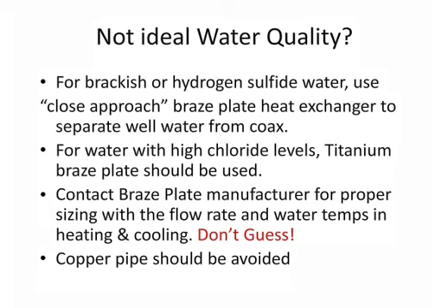Water with high chloride levels, again, you want to make sure that that close approach braze plate, I suggest, is a titanium. Always contact the manufacturer for that braze plate to have them help you in sizing for the flow rate and water temperatures in heating and cooling. This is critical because a lot of braze plate manufacturers, they produce data for you, but it doesn't get into the low temperatures you're typically dealing with for open loop.